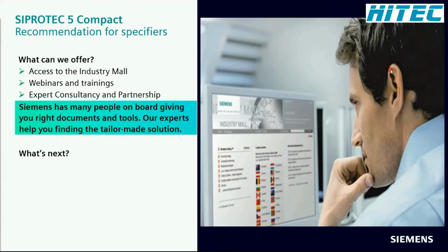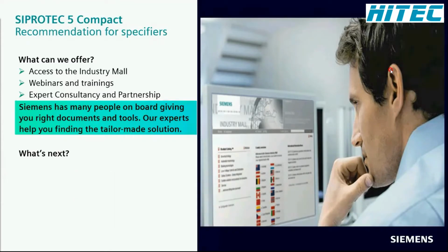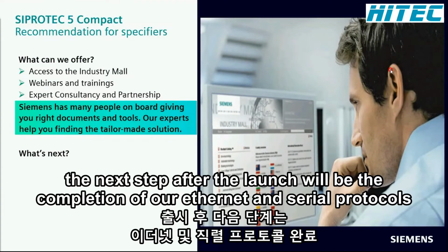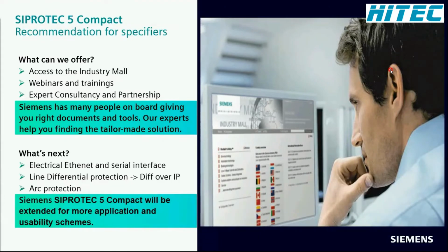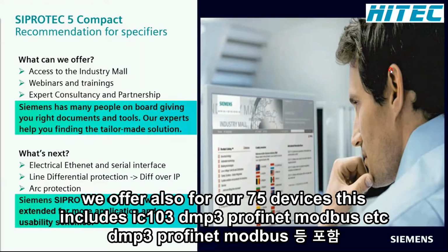So what's coming next? We already presented you a lot of cool features that we will offer with the first release, but for sure, this is just the beginning. The next step after the launch will be the completion of our Ethernet and serial protocols. As I already mentioned, SIPROTEC 5 Compact will then support the same protocols that we offer also for our SIPROTEC 5 devices. This includes IEC 103, DNP3, Profinet, Modbus, etc.